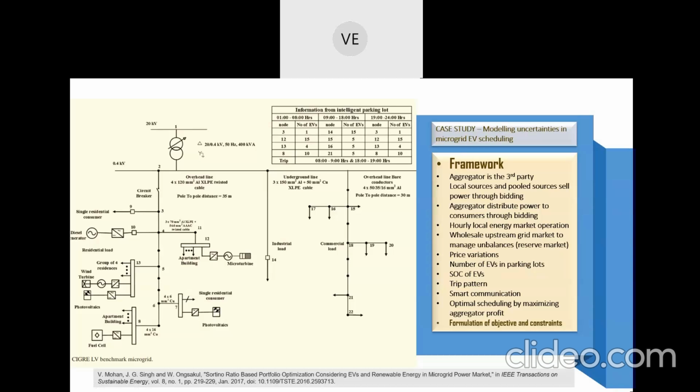So wherever there is uncertainty, you assume that uncertainties are buffered by the slack bus. That is your assumption. Now with these uncertainties in power injection, we have to incorporate these uncertainties into the load flow also, right? So slowly the deterministic load flow approach is moving towards a stochastic load flow approach.